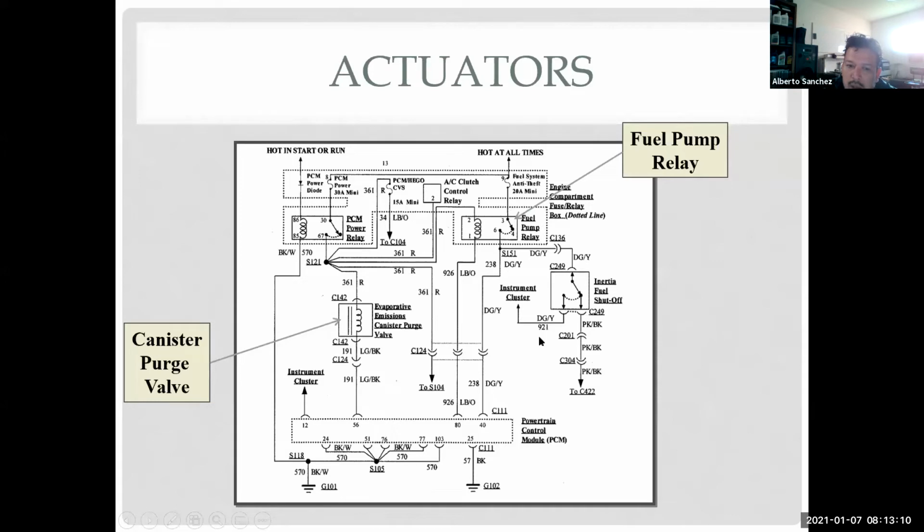In a solenoid, can the computer read, like, an input from a solenoid in case the voltage is off? Yeah. So what a lot of new systems do is, if I'm looking at this relay, for example, or this solenoid, we're going to have a sense circuit inside the computer, kind of like a DVOM. And it's going to look at what the voltage is here at pin 56. And it knows when it's not turned on, I should see system voltage because I have voltage coming down. It's going to come through my load all the way to my open transistor.